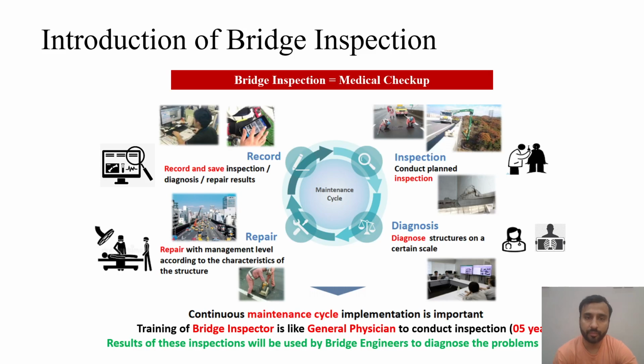The flow of the bridge inspection in the bridge management system comprises majorly four steps. It involves the database, which will have all records of inspection, diagnosis and the repairs which have previously been done on the structures. It also includes structural drawings and other drawings.